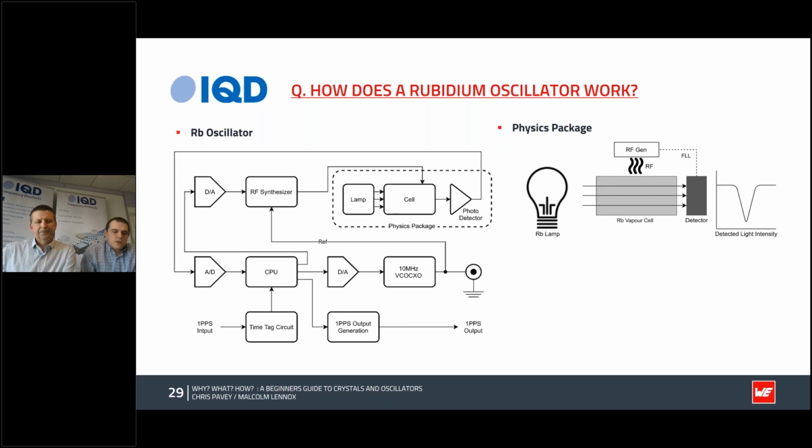This transition in quantum state, known as a hyperfine sublevel, is detected and fed back into the OCXO voltage control input in a closed loop. Any deviation from the hyperfine transition frequency will cause the voltage control input to change, thus pulling the OCXO back on frequency. In this way, a frequency stability of 5 parts per trillion is achievable.